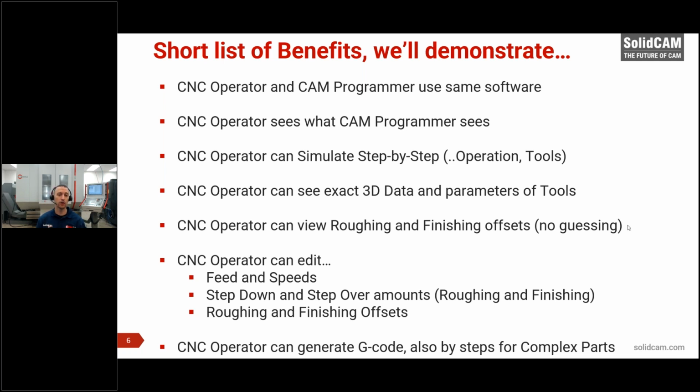As operators, we can also view the roughing and finishing offsets directly inside the software. Instead of trying to guess whether we're leaving 5 thou or 8 thou on the walls or the floors, as you learn a little about SolidCAM for operators, we can see exactly what the CAM programmers programmed for each operation as you go along. So it's really cool to know if things are going to clean up and things like that.